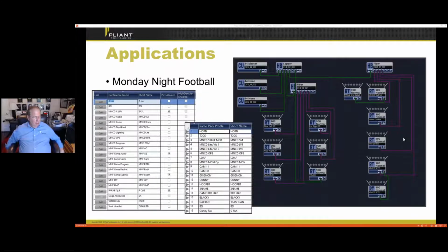Now, one of the things that they've been doing is they run fiber out, but they change the SFP. Now, the SFP is the fiber port. They are changeable. We supply them with a dual fiber LC connector, and some people have different modes of operation, and some use multi-mode. We supply it without multi-mode, just the standard connection. And we supply it that way because we understand that we can support it, but our customers should put everything from multi-mode to a single fiber that multiplexes itself.